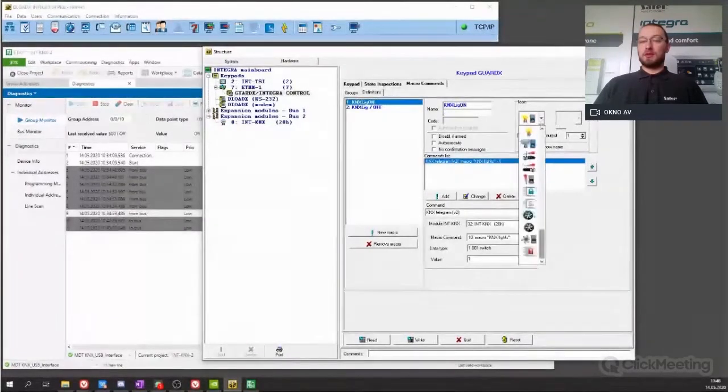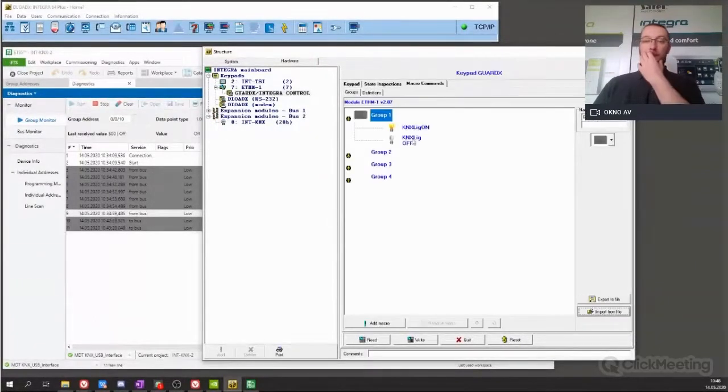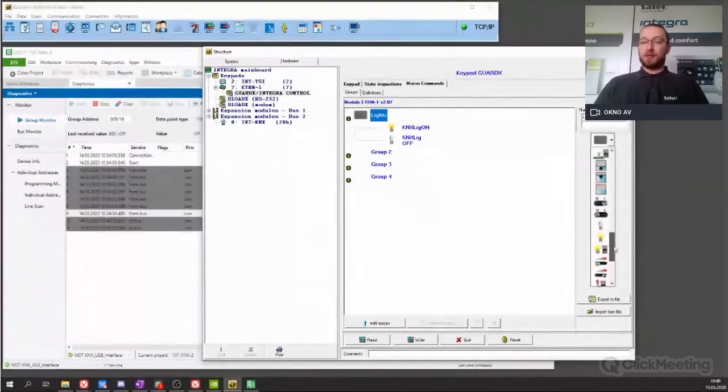In this case, I put an icon with the light bulb on. And I will name them in the group something like this and make a proper icon to finish this part. Okay, so right now I created 2 macros to 1 object to be able to control lights in the building, exactly on the group 001, which is living room.